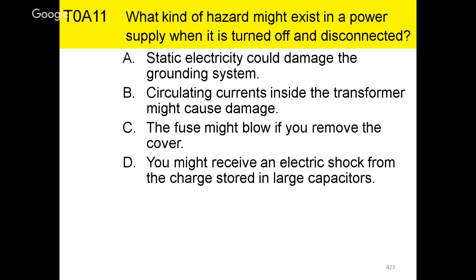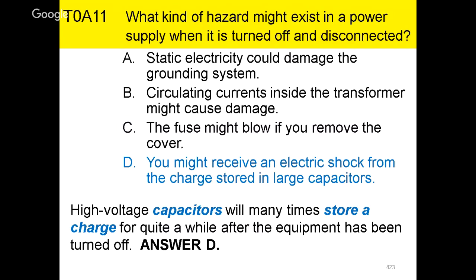Now, I kind of touched on this topic before. Again, we're talking about those nice little sneaky capacitors. They have a capacity to store some electrical charge. Especially the high voltage capacitors, they'll many times store a charge for quite a while after the equipment has been turned off. There are some techniques that you can use to make sure that the capacitor is discharged properly.